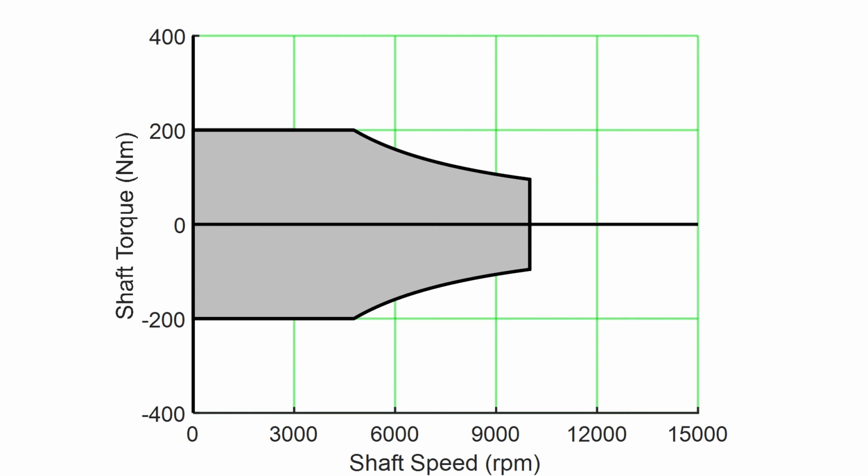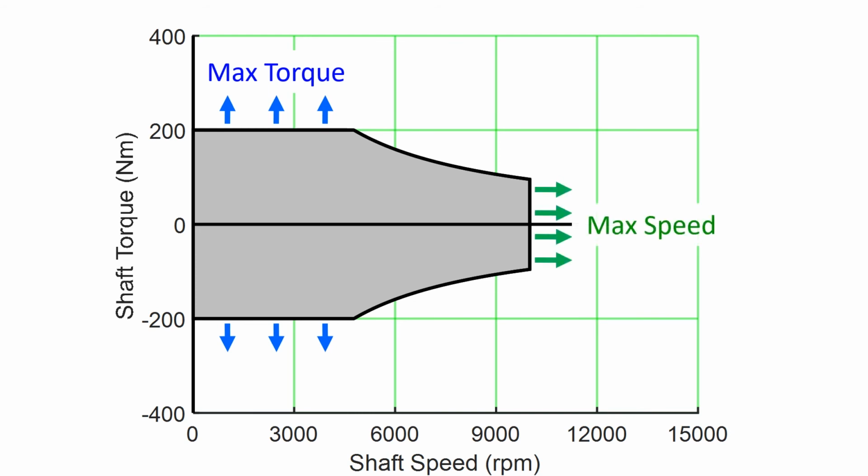The operating region we need for an electric drive system is specified via the requirements we put on the electric machine and the power electronic inverter. The main parameters are the maximum torque, and it influences the operating regions as shown here. Secondly, the maximum speed of the drive. And finally, the maximum power. These three parameters can be chosen rather independently of each other.